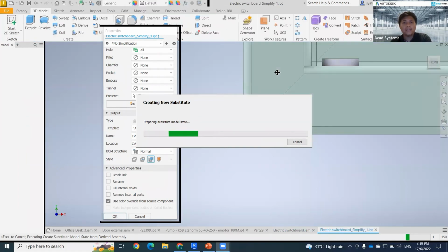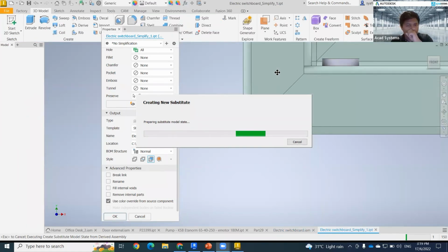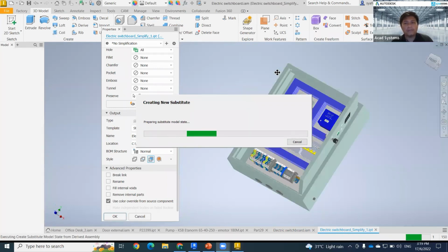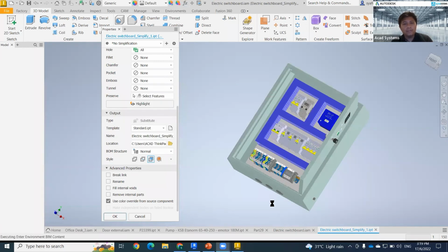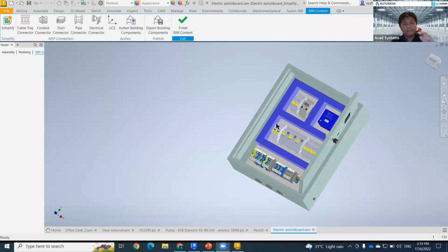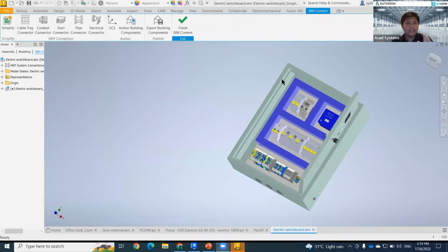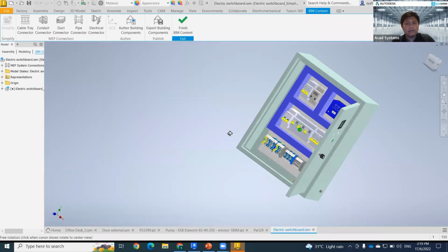Normally people will just import using Revit as a step file. The problem is later you will face this issue: your file will look a bit heavy. For example, I have a downlight from a step file that I want to transfer to Revit. What problem do I face if my building has thousands of lights? My project later will consume a lot of memory and also space.